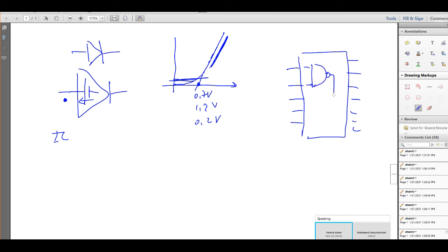Yeah, NAND gate like that, and I need to do A bar. So I can do this A bar. For A bar, we should have the inverter, another IC, and they call it inverter, where we have only inverters inside. 1 in, 1 out. Here we have NAND gate, and this is one of the exercises that will be done later on in the next experiments.